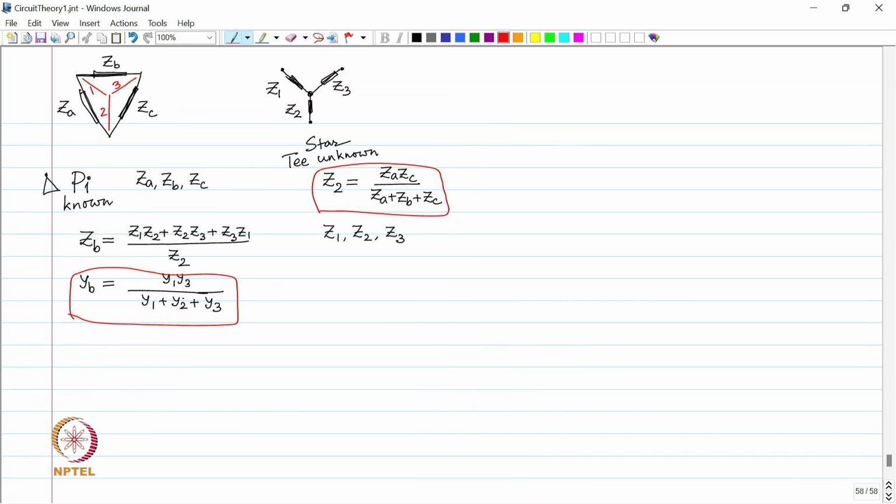9, 9 and 9. So, 1, 1 and 1 in series is equivalent to 9, 9 and 9 in parallel. Okay. So, if I want a series network to be the same as a parallel network, then the resistance has to be much lesser in the series network. In the parallel network, you will have large resistances. In the series network, you will have small. Fine.